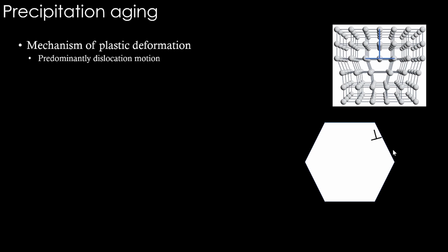Similarly, there can be a phase like this, and dislocation meets that phase and it will be blocked. This is an interface. This is also a grain boundary between two phases. We have this interface, and this also can block the dislocation. So if this can block the dislocation, why don't we have this second phase more uniformly distributed in a fine manner like this?